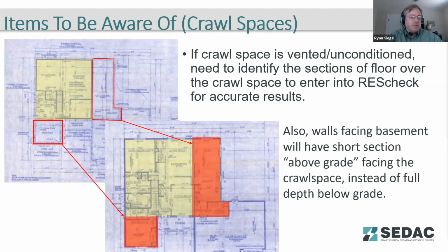A lot of the trades we're seeing are moving more towards treating crawl spaces like short height basements. Seal them up, manage the water, go ahead and ventilate them, and bring those into the thermal envelope. So doing unvented and conditioned crawl spaces, mini basements, if you will.